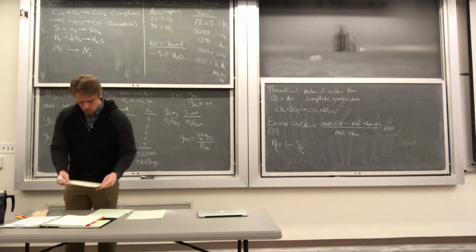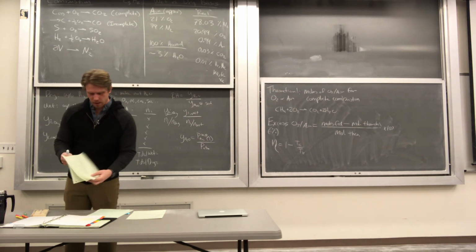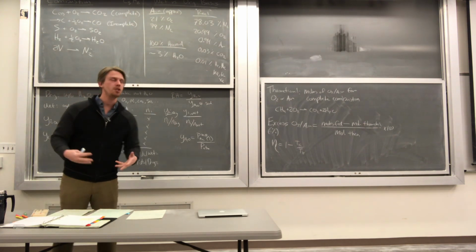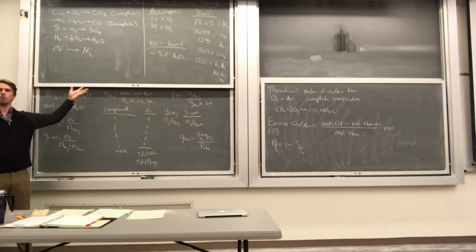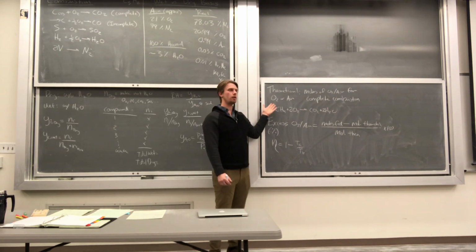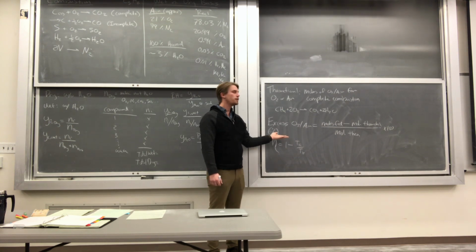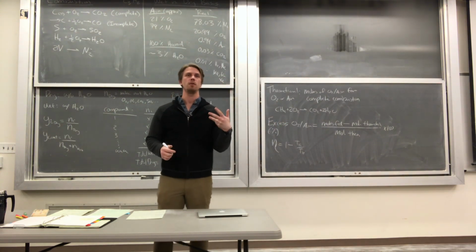Okay, so what I have left is, let's see, I have an example, but I may table that until Monday. It's really just an application of these definitions. Combustion is just a subcategory of the reactions. The tools we have are identical. The nomenclature is a little bit unique, because we say theoretical oxygen or air, that's the amount we need for total combustion. We should think of this as the stoichiometric ratio. Excess is the same thing as an excess reagent. But since combustion is such a prolific chemical reaction, it's developed some of its own nomenclature.